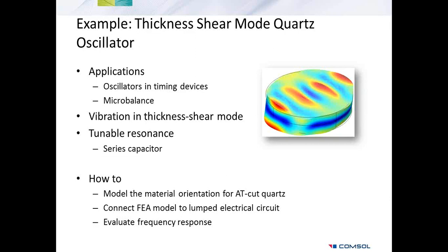The important modeling steps here include setting up an appropriate coordinate system to implement the AT-cut and finding the method to combine the finite element model with the lumped electrical circuit model, which can be used in turn to introduce the series capacitor.